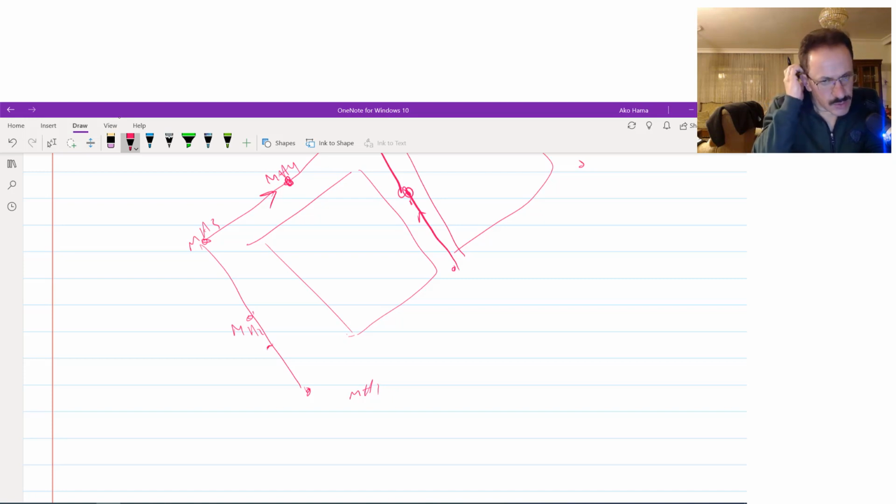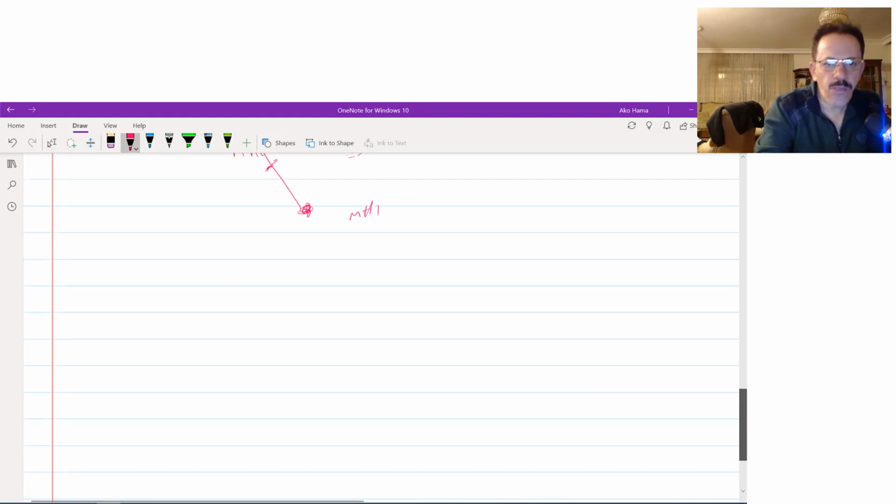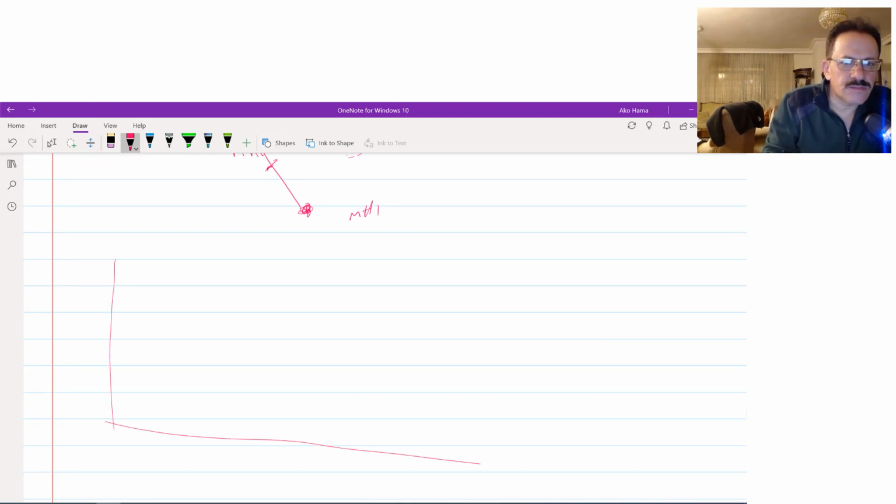We have to start with the first manhole. We need its dimensions and bed level, and you have to draw a profile like this. And this profile will look like this, and you will say this is the manhole number, these are the stations. You have to allocate the stations for this one.